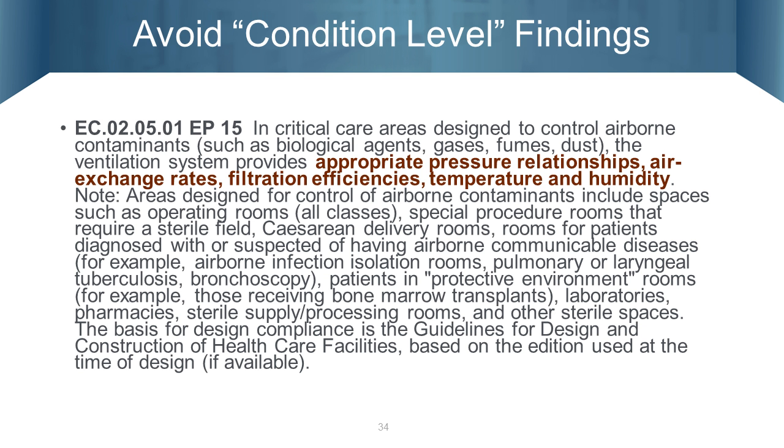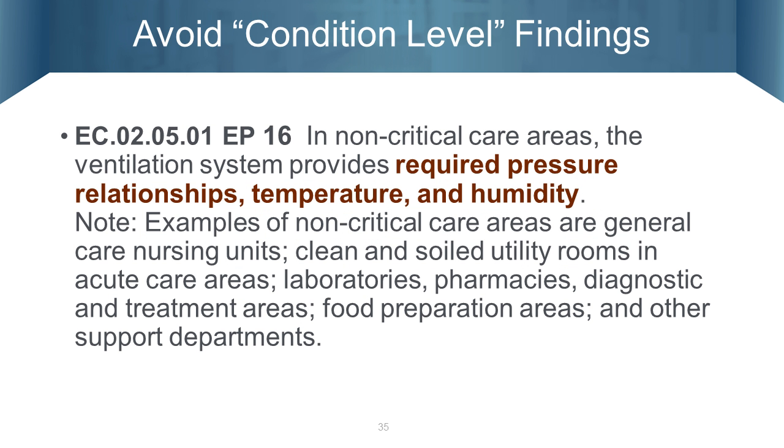Many times it's in sterile processing, in the decontam room, and we can talk offline about why that's happening. They're following AAMI guidelines, which have a totally different temperature requirement than the FGI guidelines. You need to follow the guidelines that the space was built under and then maintain those temperatures and pressures appropriately. I think that's enough said for that one.